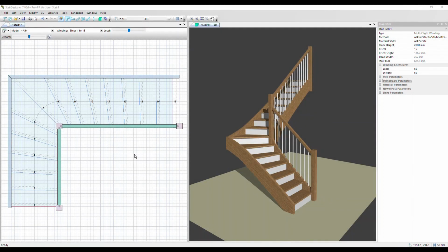In this video we'll look at the general Stringboard parameters. We've got the whole stair selected in the Properties menu. Like this you can see further options, Stringboard parameters. Let's click on the plus icon to open it up. We have a sub method. This is a set of pre-configured settings for the Stringboard. We'll look at this elsewhere. Let's just leave it on default for now.